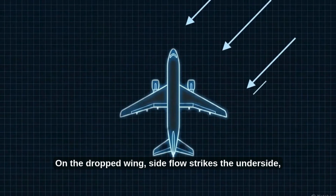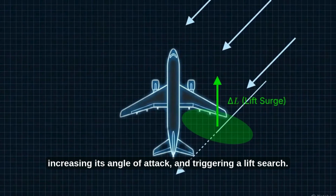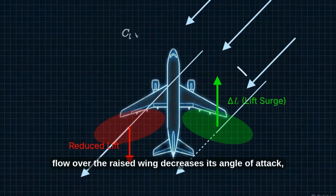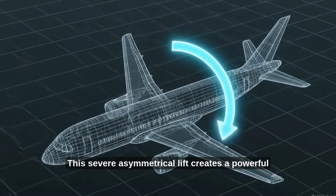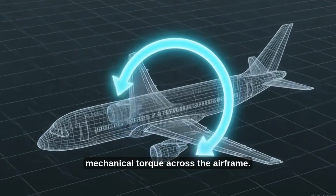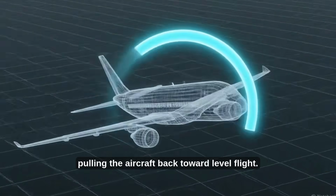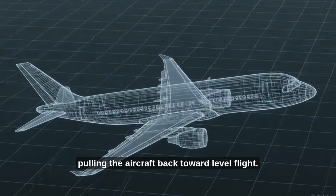On the dropped wing, side flow strikes the underside, increasing its angle of attack and triggering a lift surge. Conversely, flow over the raised wing decreases its angle of attack, reducing lift. This severe asymmetrical lift creates a powerful mechanical torque across the airframe. This is the restoring rolling moment, pulling the aircraft back toward level flight.